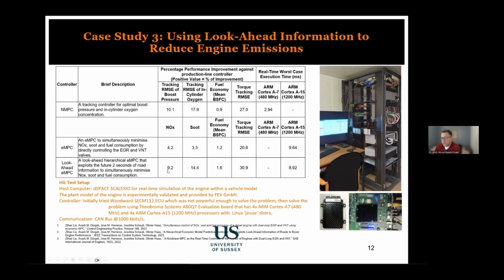So this 9% and 14% is just the effect of considering the data in the future. And it's good to note that NOx and soot are contradictory. There is a trade-off between them, and improving NOx normally degrades the soot emission.